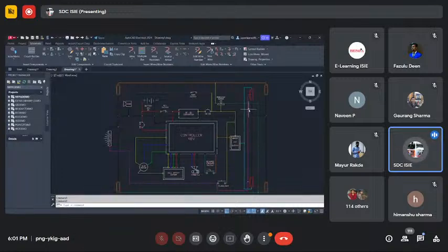Along with that, we have connections for the auxiliary components, like the purple and blue wires for giving the 12 volt power supply to the backlight. Along with that, we are connecting a power supply of purple color to the headlight. And you can see the black wire is common to all of them. They are connected to the 12 volt common connection in this particular circuit. This is a circuit of the basic primary connection of a wire harness of a two-wheeler.